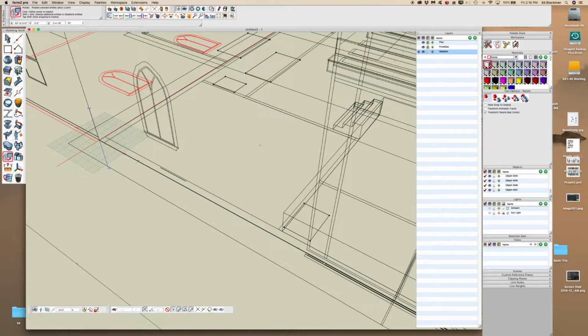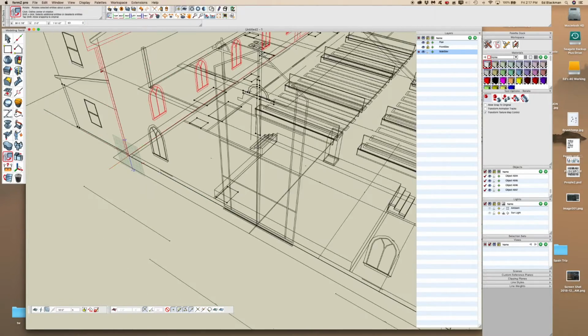Now we want to rotate it up. So we go down here. Now this time we're going to be rotating it in the other direction. So see how these planes work for you? So you still got your rotation tool, and over here, just so you notice, this is making no copy. This could be a copy and a move. This is multiple copies. I'll show you that later. But go down here and click on this. And it doesn't really make any difference. You don't have to be on the elevation at all. You can be up here in midair if you want to. But you want to rotate it around this direction. And so there you have it.